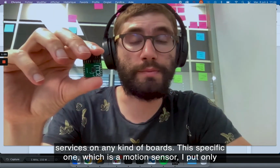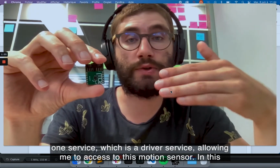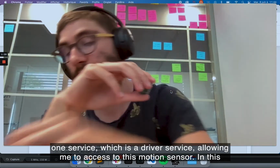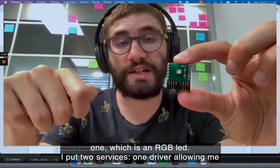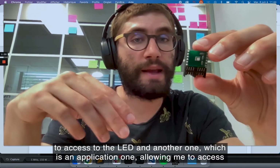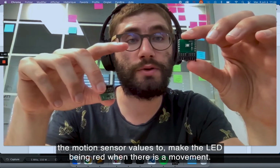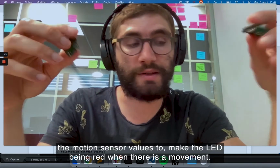On this specific one, which is a motion sensor, I put only one service, which is a driver service, allowing me to access this motion sensor. In this one, which is an RGB LED, I put two services: one driver allowing me to access the LED, and another one, which is an application, allowing me to access the motion sensor values to make the LED blink when there is a movement.